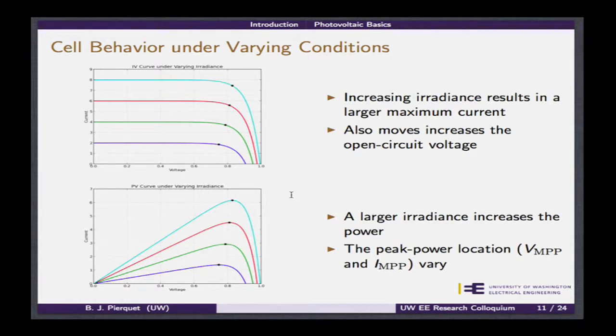And in this case, when you decide to interface to this, you have to be the one as a power converter or as a circuit trying to figure out at what voltage do I need to run in order to have the current be at the point that it's needed to get the maximum power out. And so there's actually an active feedback role in the conversion process in order to get the converter operating at that point.